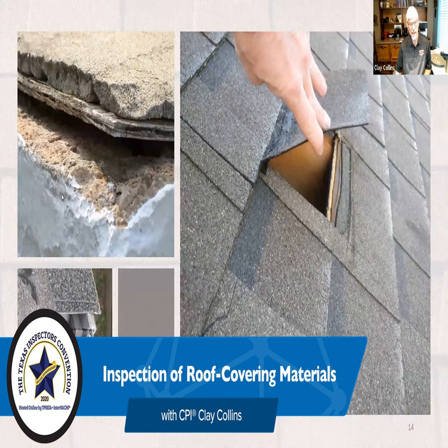All right, to answer step flashing, the code was changed to allow what is called continuous flashing, which may also be called hemmed flashing, because the J is laid flat and it looks like a hem, and then it can be called J flashing. Well, the problem is that this shingle is not flat, and the manufacturer says my shingle needs to be laid flat.